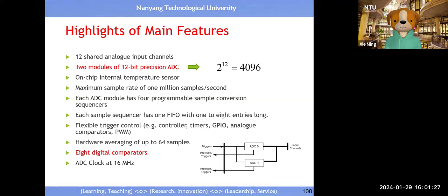And since we allow you to attach 12 sensors, they ask, why not offer me 12 jumping devices, making my life easier? Sensor 1 goes to jumping device 1, sensor 2 goes to jumping device 2. Make my life easier, yes or no? But because of the low cost, you do not have 12 jumping devices, you only have how many? 8. Okay, remember all these numbers. 12 sensors at the input, you only have 8 jumping devices.